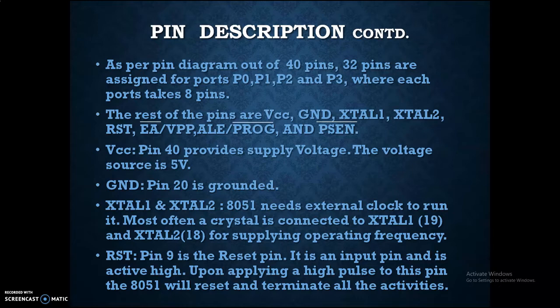Coming back to the RST pin, pin number 9 is the reset pin. This is an input pin obviously, and it is active high. When we apply a high pulse, that is positive voltage, the 8051 will reset and terminate all the activities, and it will start executing from the beginning, that is 0000H, or the beginning of the program.